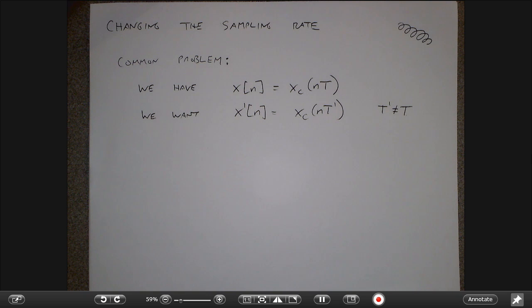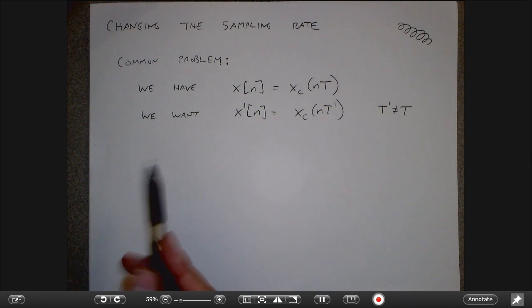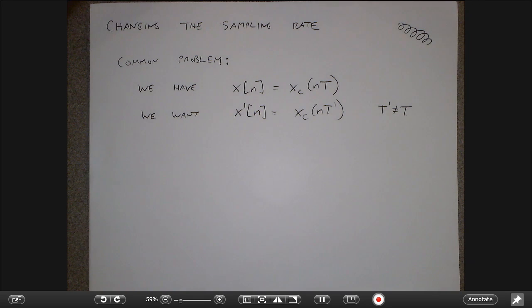So assuming everything is sampled above the Nyquist rate, in theory, there's the long way around. What I could do is take my samples, reconstruct the original continuous time signal, and resample it to get back to the digital signal. That is true, I could do that, but that seems needless. Because really what I want is a fully digital operation that goes from the original samples to the new samples. And I may not be able to create analog signals inside my processor anyway.